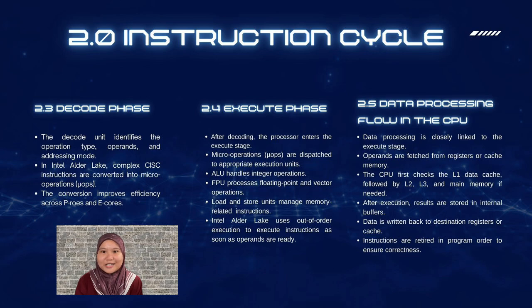This execution model helps maximize hardware utilization and minimize pipeline stalls caused by data dependencies or long latency operations. To ensure correct program behavior, the processor relies on mechanisms such as reorder buffers, reservation stations, and dependency tracking logic, which collectively preserve precise exceptions and maintain the correct architectural state even when instructions complete out of order.